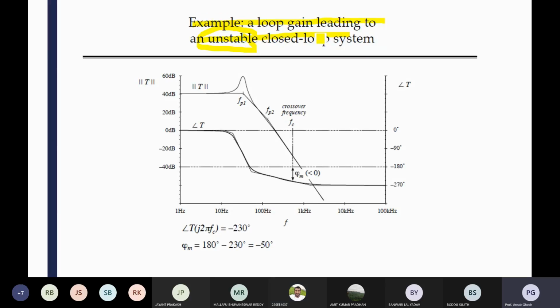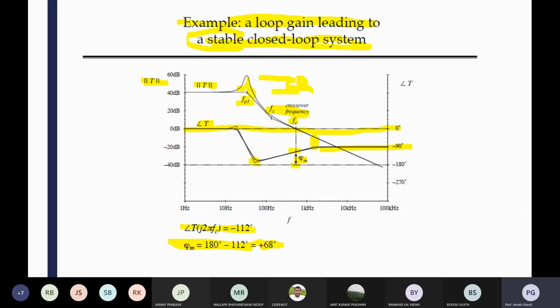So actually, what happened? In this subject I am giving some of the mathematics, some of the theoretical analysis, theoretical aspects. If you have some experimental result with you, we can define it, but some response is there in my next slide, so you can understand. There is some direct relation of phase margin with your damping factor, that zeta value. Are you getting my point? So in your previous example, you can see that phase margin is coming in the range of 68 degree, nearer to 70.